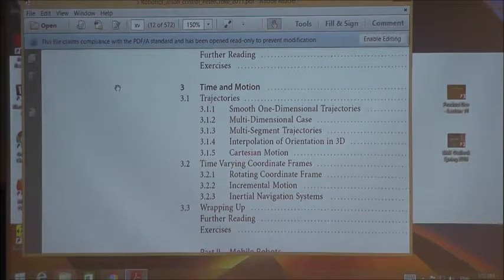Now the reason you do that, as you all know, you have all taken control classes before, is that almost the entire classical control system is based on linear systems. A lot of the time, linear time invariant systems, where you can even use the Laplace transform. Or if you take the discrete version, like the course I'm teaching in the fall, use the Z transform.